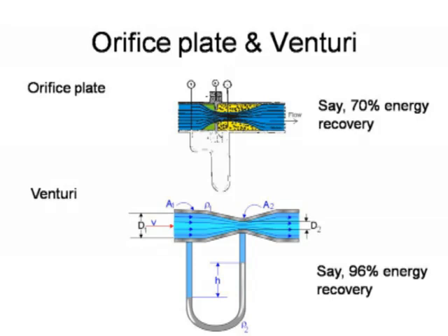Most of the turbulence and most of the pressure loss is in the yellow illustrated section where the flow is in fact beginning to expand again. And that is the sort of shape of the venturi. The venturi in fact has a fairly short lead-in section and a fairly long lead-out section, which isn't illustrated very well in the lower diagram.